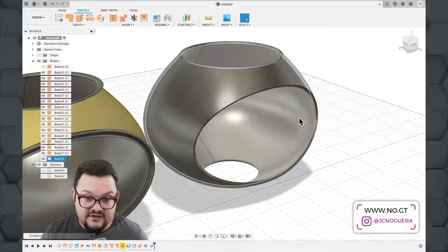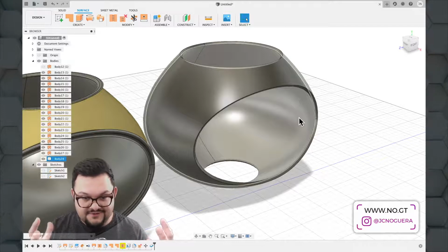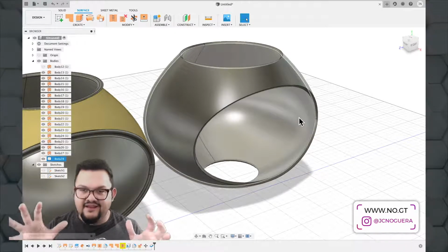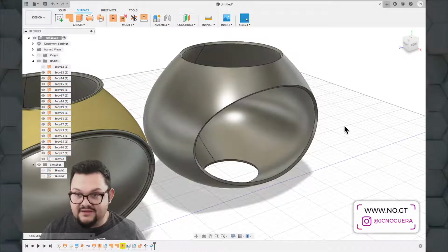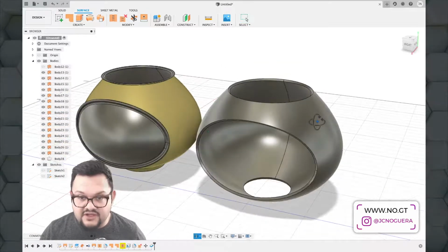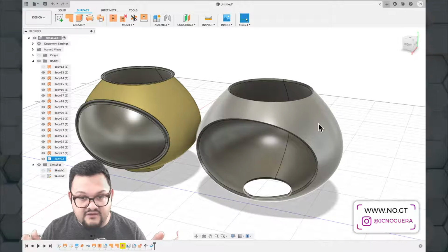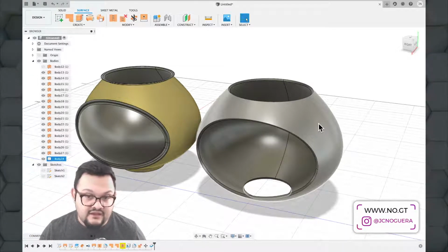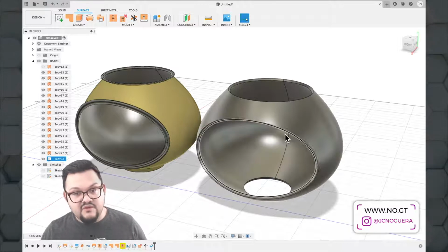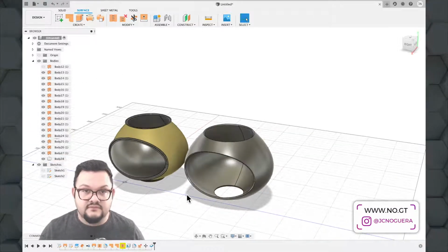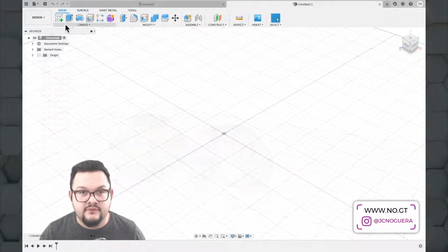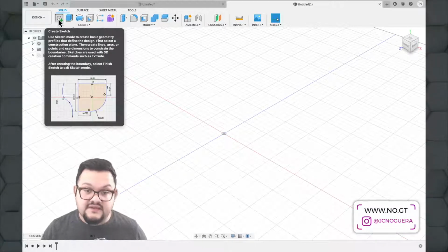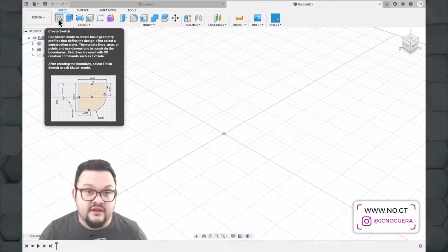So let's say I wanted to create a silicone jacket for this object. I can go ahead and grab that outer skin, and I can create a new object based on it. So you can go back and forth, copy things, move them around, use them as cutting tools, use them as tools to be cut. There's really a lot of flexibility in what you can do with all the surfacing tools. And surfacing tools are great things to create very irregular, complex geometry and complex curvature.